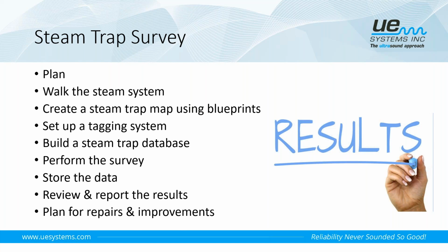And again, depending on how serious we need to be as far as making the repairs and improvements, we're able to put a dollar amount to it. So we can say, hey, if we repair these traps or if we change out these steam traps, then we're going to realize this savings. And that becomes critical in making these plans for the repairs and improvements. And who knows, maybe we find enough wasted energy on our steam traps that are failed or failed open to where we have enough left over to do other types of improvements.